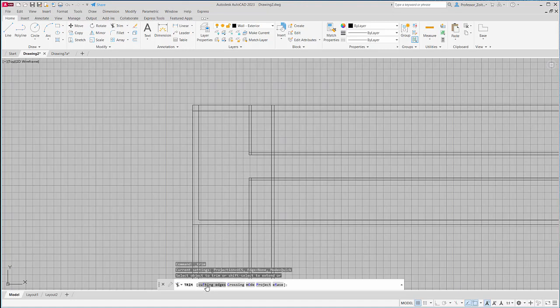I'm going to select the cutting edge, and this line represents the cutting edge of this line. Notice on opposite sides of this wall, the wall thickness changes from 8¼ to 6½. So I'm going to pick the cutting edge here, press enter, then I click on this entire line and it disappears without me having to do multiple clicks throughout this whole region.